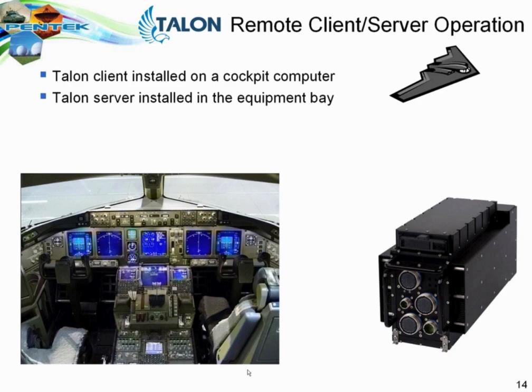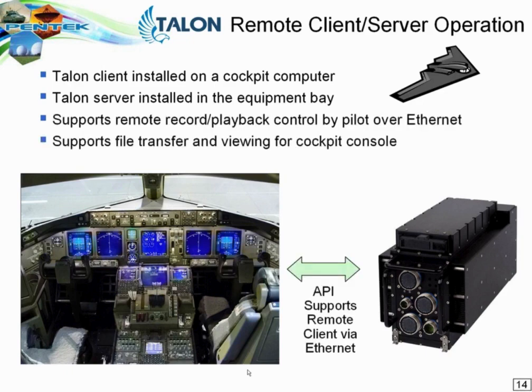If we go to the playback screen, again, very, very easy to use. What you do is specify the file name, the starting position in the file you want to play back, the transfer length in seconds or megabytes, and then you simply hit play. In this case, what we would do is fetch the file from the solid state or the magnetic disk and send it out through a D to A converter to reproduce the analog signal that was recorded.